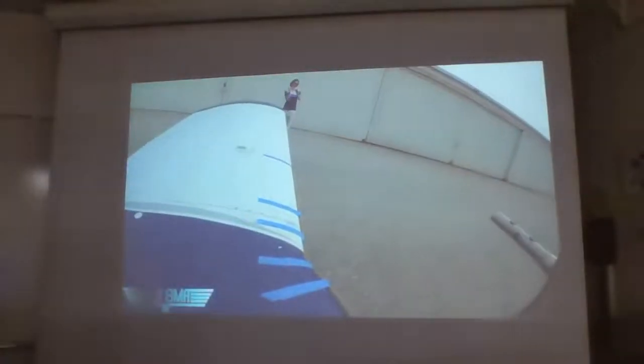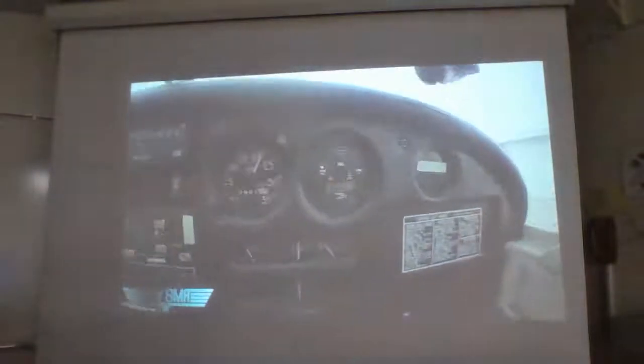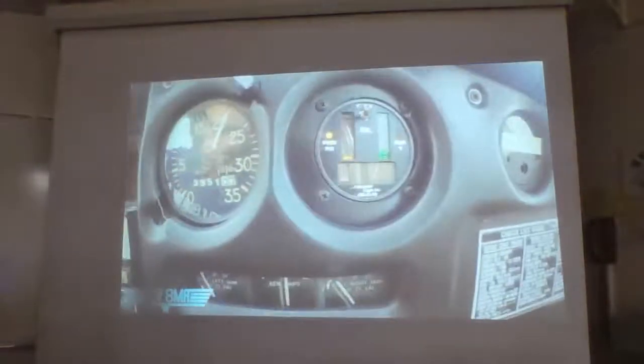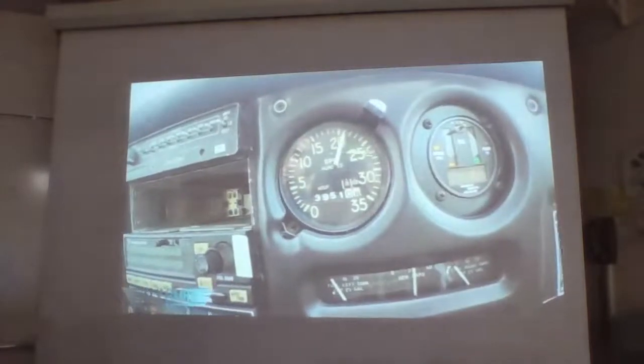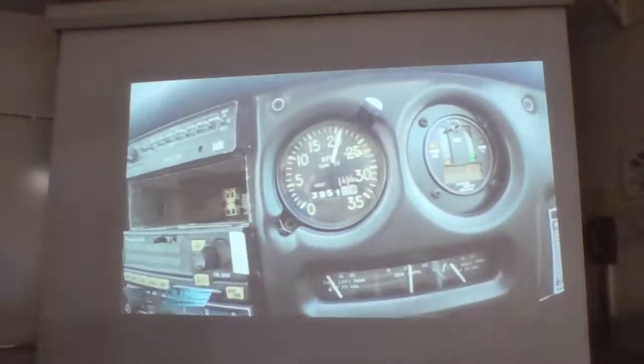And it looks like that is really just pumping air right now. So I'm guessing that, yeah, the sump is totally out of oil. We're down to 1 pound of pressure. And you would probably be in big trouble right now. We can see we're slowly losing some RPM there, 2,100 RPM.